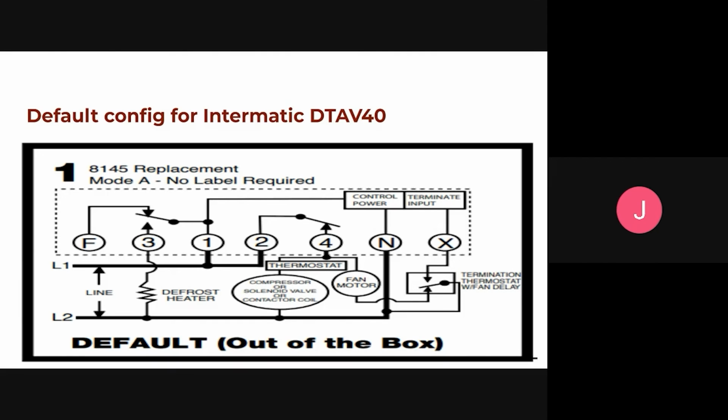Right, and it also just gives that time. You don't want frost or ice to build on that coil before the fans in refrigeration come back on. That's where that drip time comes from. And yes, the fan delay can be the same thing. It keeps it from blowing the water out, because you can have an ice skating rink on those floors if you start blowing that water out of that coil. Yeah, I've seen it, experienced that.